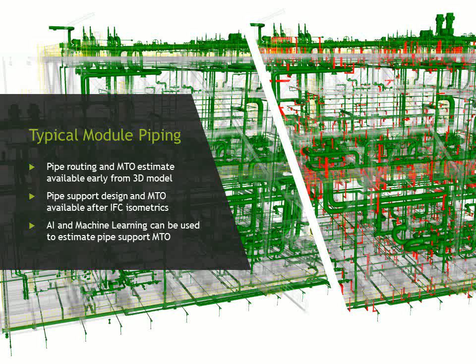While the routing may be tweaked here and there to optimize the layout within the space available, the piping material takeoff will not change very much. The pipe support design, however, can change drastically with a small change in pipe routing. Two pipes may be brought closer together and two smaller supports may be combined into a larger support. Pipe stress analysis may require moving or adding supports, or changing the type of support.